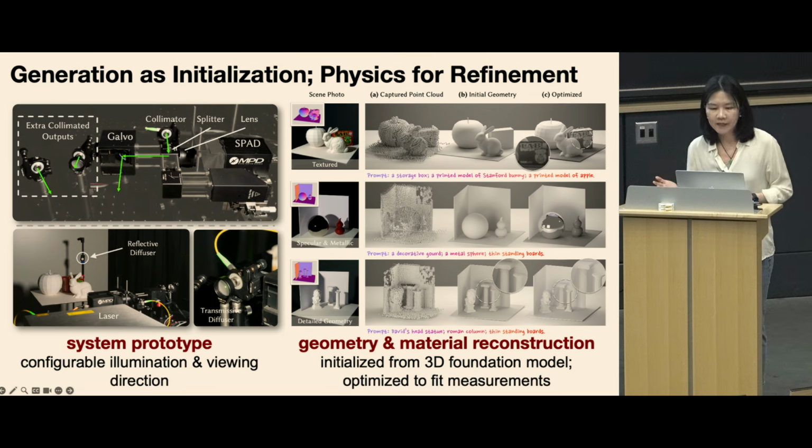Hardware-wise, we have designed a scanning system to simultaneously support lighting and imaging. We first coupled the laser into a fiber and put several collimators at different locations in the system. So we put the collimator behind the splitter, and we form a confocal ToF scanner.